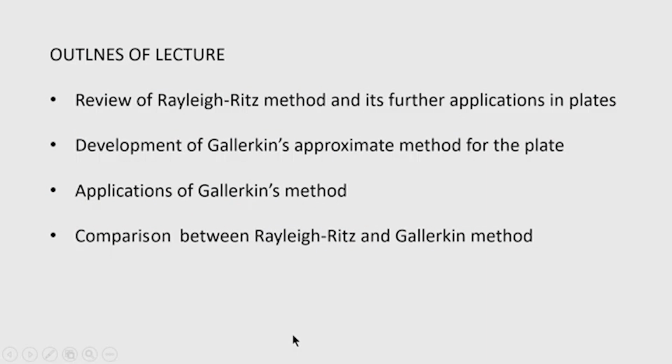So, the outline of today's lecture will be: review of the Rayleigh-Ritz method and its further applications in plates, development of Galerkin's approximate method for the plate, application of Galerkin's method, then comparison between Rayleigh-Ritz and Galerkin method.